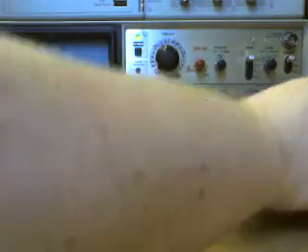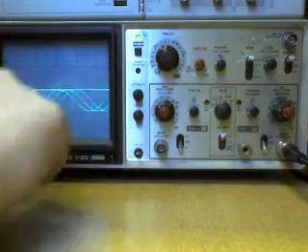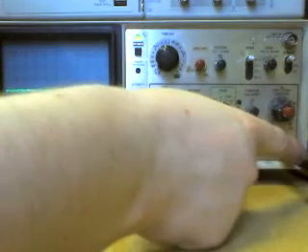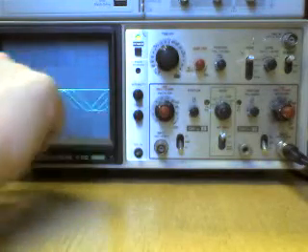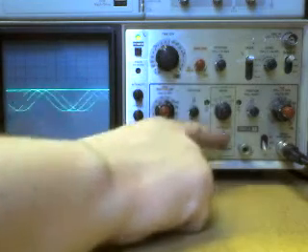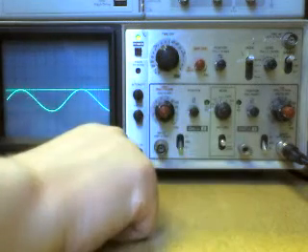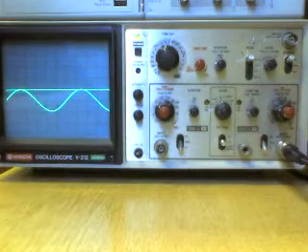And if we move this over to channel 2, we DC couple this. Okay, now then, because we moved over to channel 2, you have to make sure that your trigger is set to channel 2. That's just below the mode. So you've got channel 2 here. Next one down, there's channel 2, and it's triggered because it already had set up to trigger.